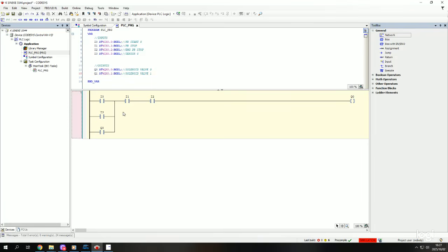Then our circuit needs to change. So our ladder logic diagram needs to change. This is our push button for advancing the piston rod, our emergency stop, as well as our push button stop. So we need to introduce what? Our sensor, which we gave a label, we defined it as I3. So I3 must sense the fully advanced position.